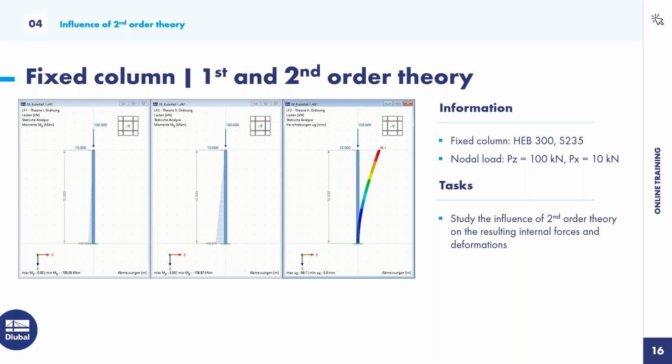So if you have slender or flexible systems, you want to at least investigate the influence of nonlinear deformations, of the deformed structure instead of the undeformed structure, on the internal forces and reactions.